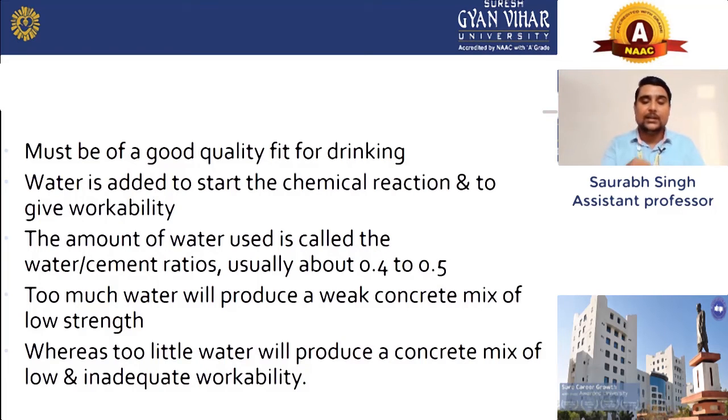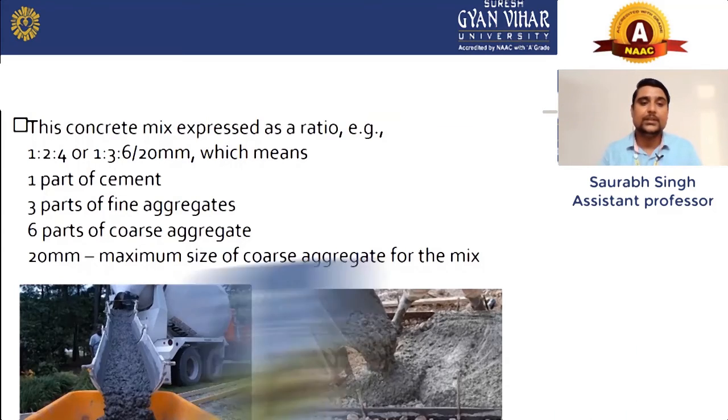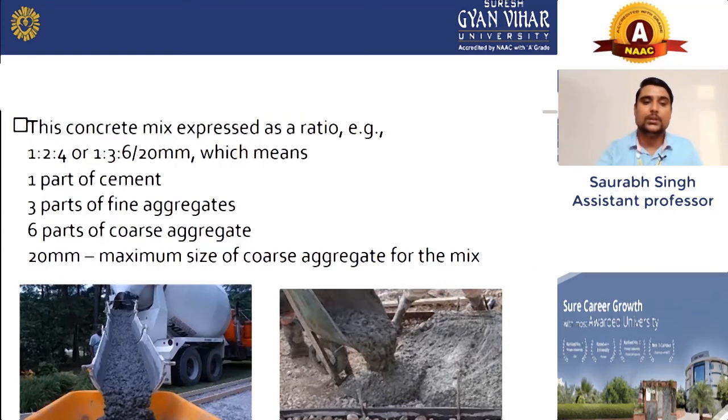It should vary from 0.4 to 0.5. You cannot use too much water in your concrete, and you also cannot use too little water. You have to use a proper proportion of water in your concrete, then you will get good strength and good workability.